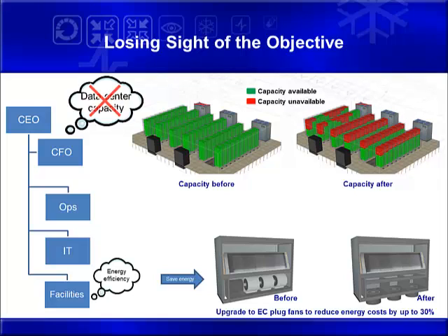Many of the U slots have turned red because one or more of the IT resources is not available to the entire IT plan. In this case, cooling is the limiting resource. The new fans move some of the cooling from the IT plan to where it is not needed. This cannot be seen or measured. This is a problem because on a later date, operations will install IT equipment where cooling is supposed to be, but they won't know that it isn't there until they install and turn on the equipment. In this case, 75 kilowatts of fan power was saved, but 120 kilowatts of capacity was lost.